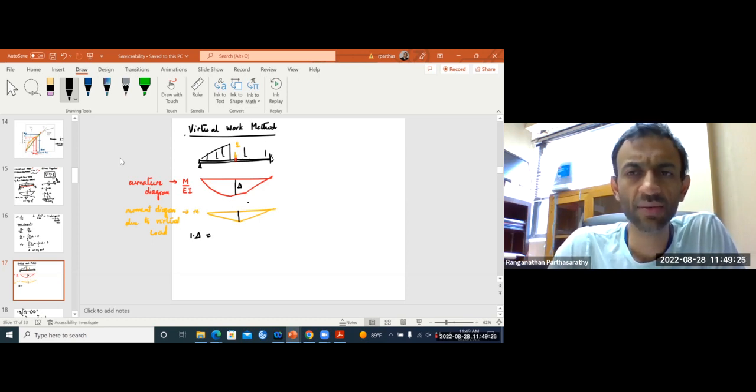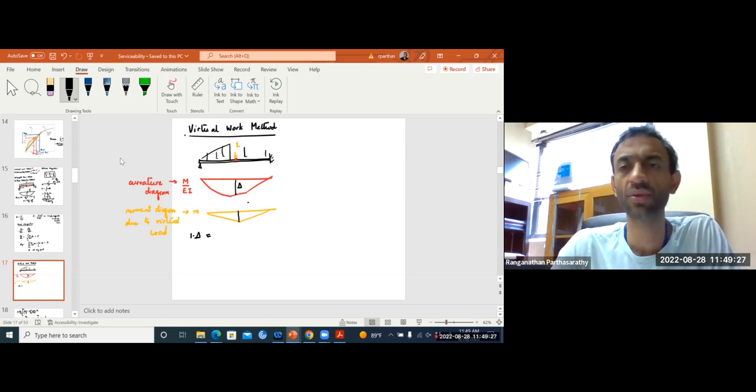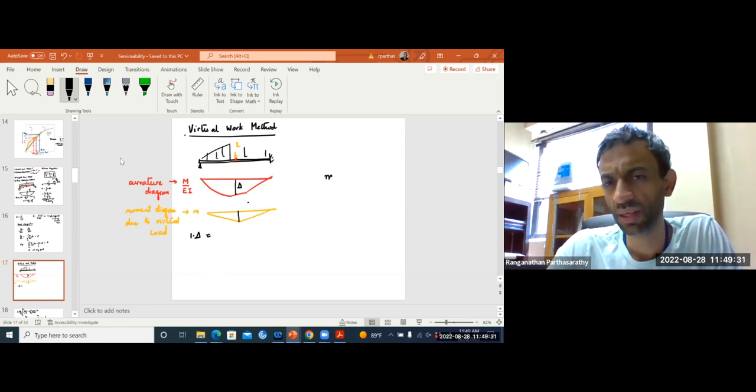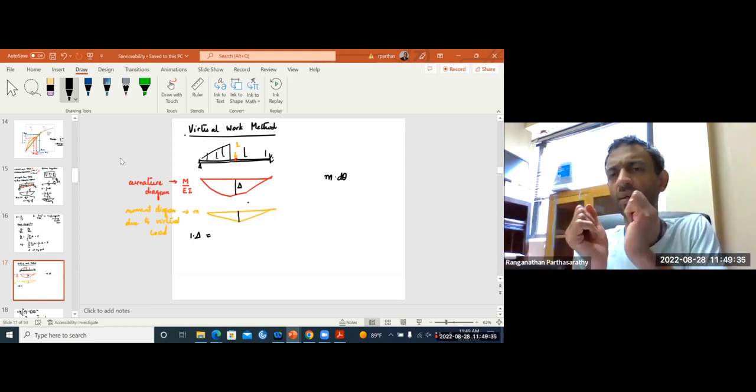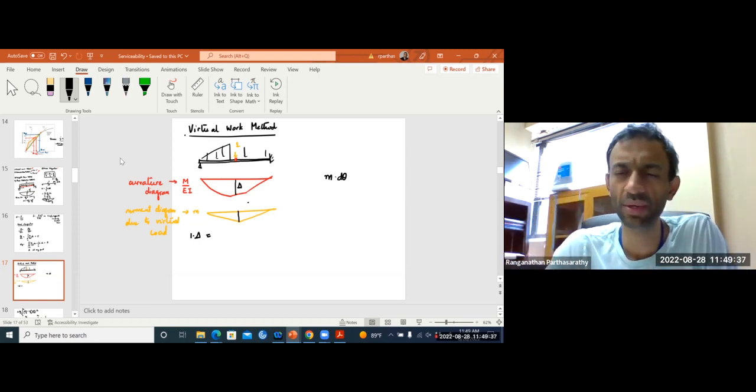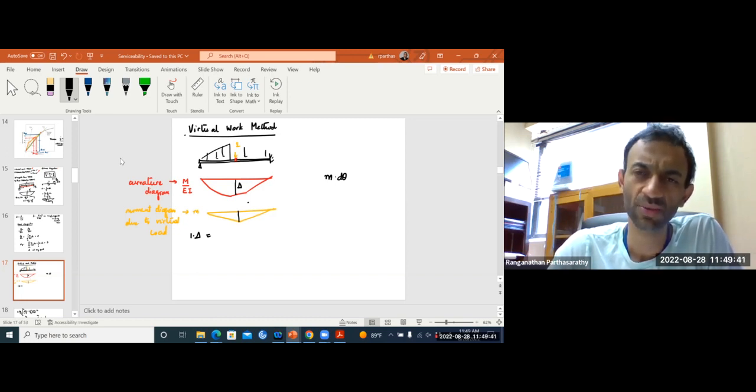What is your internal virtual work? It's the energy. So energy is moment times d theta, right? Moment times change in angle, bending. That is your work done by moment, right? Force times displacement, moment times rotation. That's work.